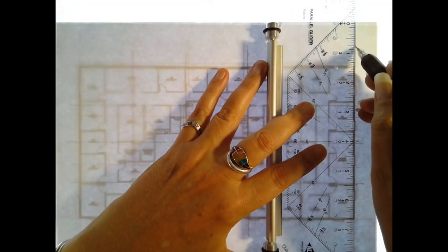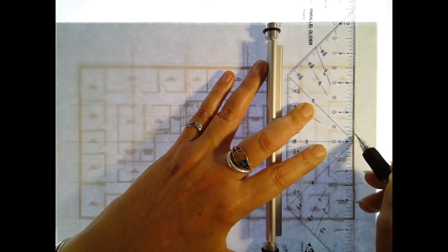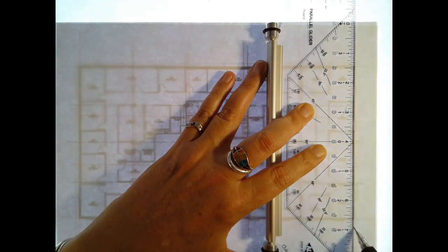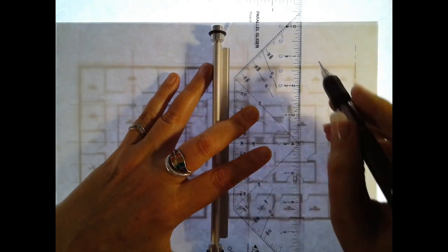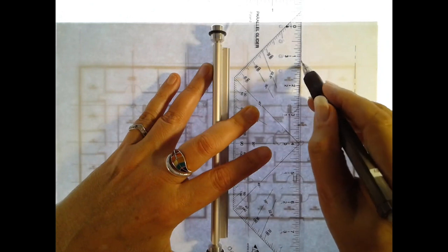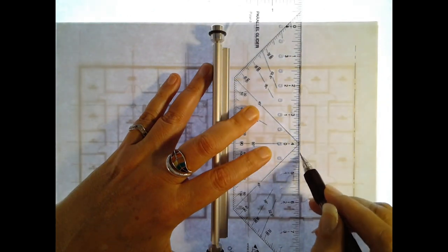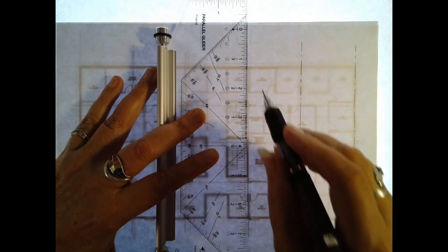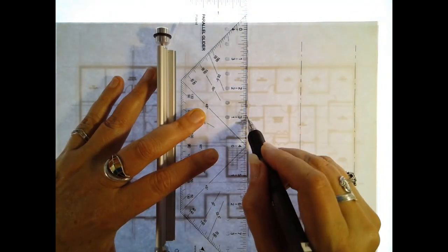Just one comment about column grid lines. They are drawn as light dash dot lines because that is to clearly differentiate them from other line work in drawings. The column grid is a background element to all drawings in a contract document set because they underlie not just architecture but structure, mechanical, electrical, plumbing.